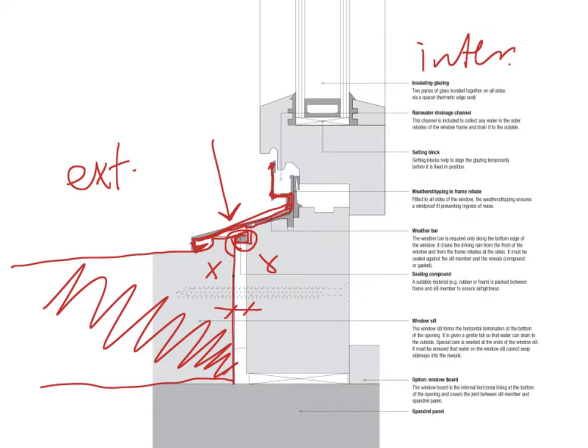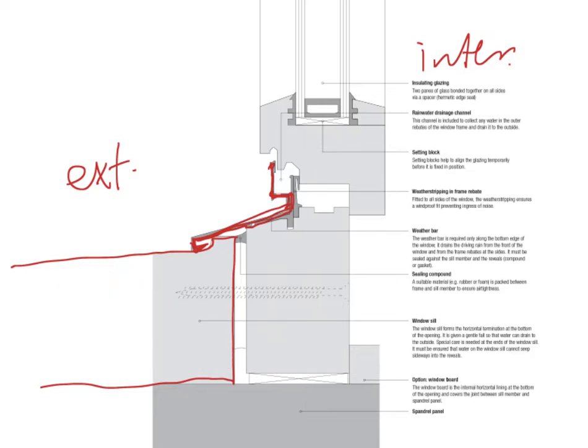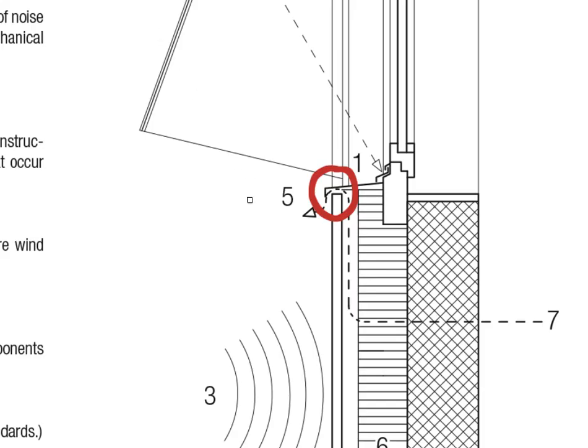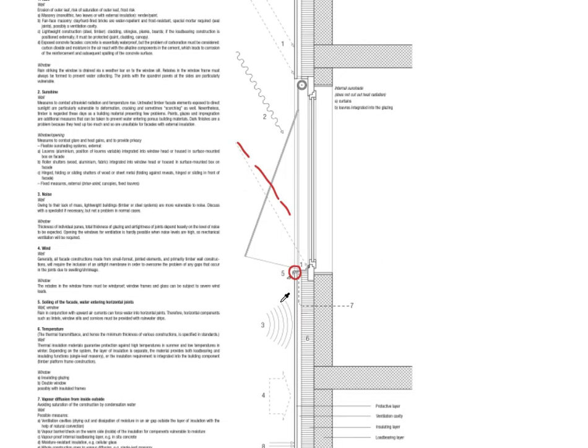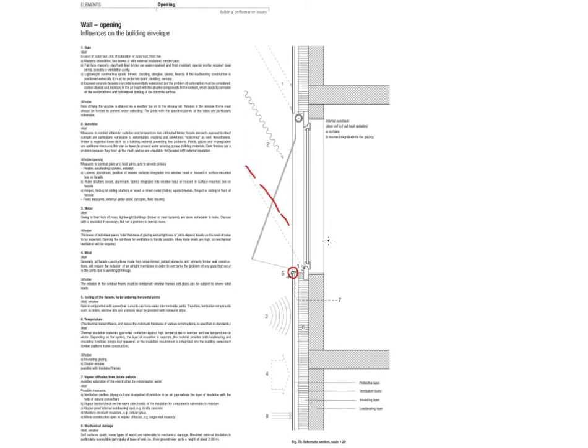So these type of materials are not completely flush, because as you know, not everything can be manufactured or assembled on a site as precisely as you were to draw it in a detail. So you have to consider these kind of moments where things might not match properly, and you have these little tolerance gaps in it as well. So yes, I think these are some of the most important things to consider when detailing windows.